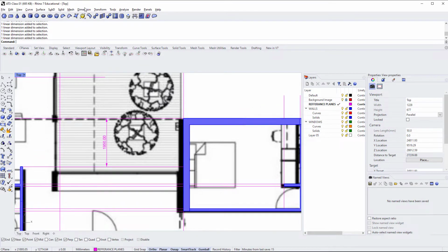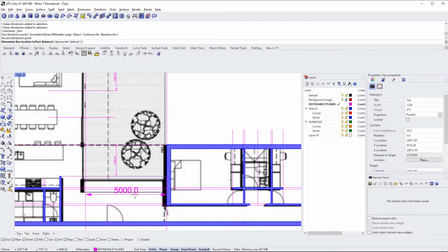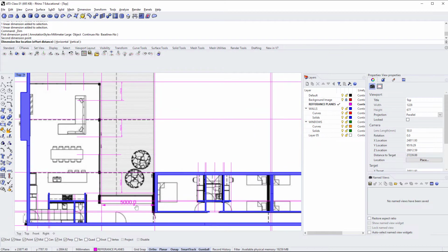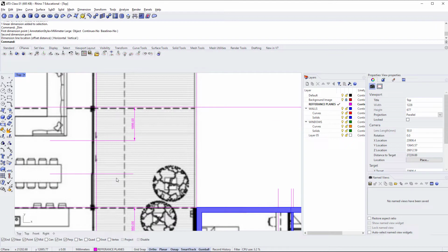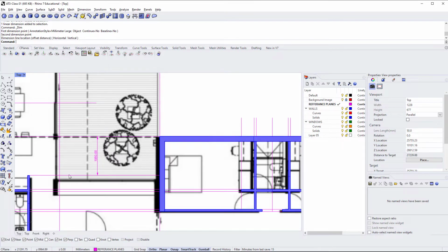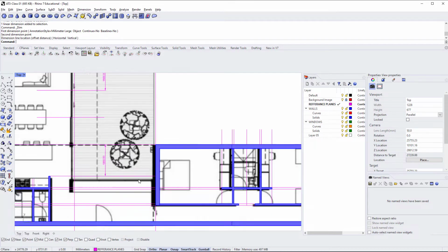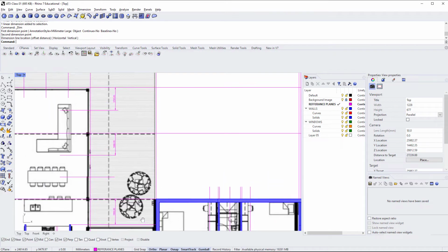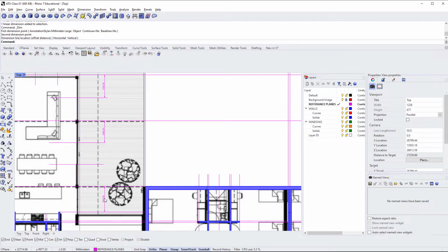So between this point here and this point here, that's 5 meters, I would probably be doing something similar to what we did here, considering this is a 5 meter bay for these sliding doors using 1666. That would make sense. You then have 3 panels at this point here, and now we've really only got 4 different types of glazing sizes if you account for this one glazed wall. If you don't count that, it's only 3 different glazing panels that need to be manufactured.